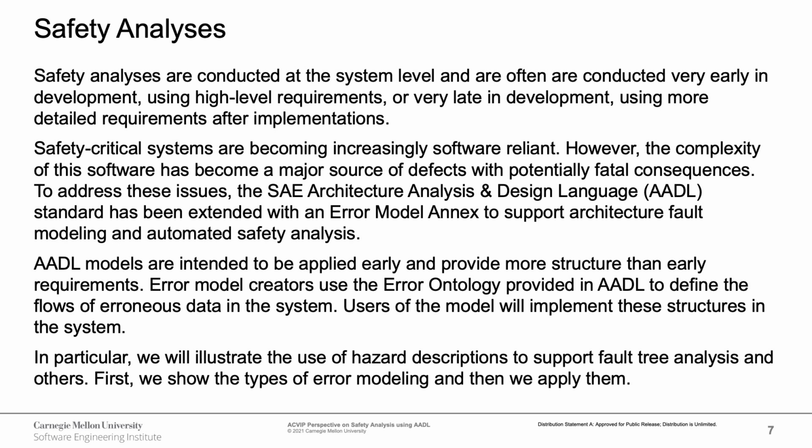Current safety engineering best practices, such as DO-178B and C or SAE ARP 4761, are labor-intensive and only performed as part of the system engineering process. At the same time, increased interaction complexity of the embedded software with the hardware platform and mechanical system has resulted in the software being a major source of defects with potentially fatal consequences.